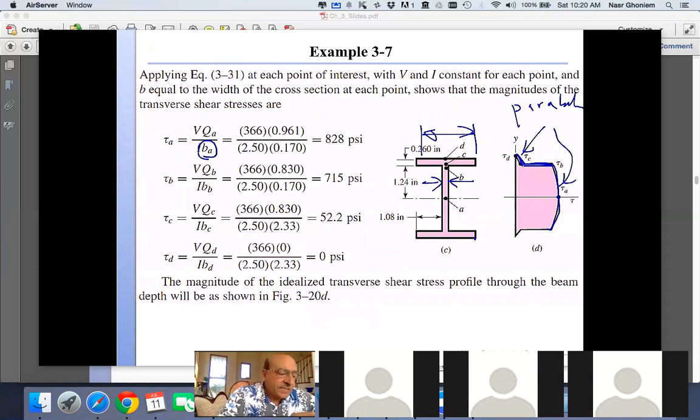So the moral of the story is that the bending stress would be the largest on the top or the bottom. That's an axial direction, while the shear stress will be the highest at the center. So for beam design, we don't know where would be the failure point. It could be a result of the axial stress at the top or bottom, or it could be a result of the shear stress in the web section.